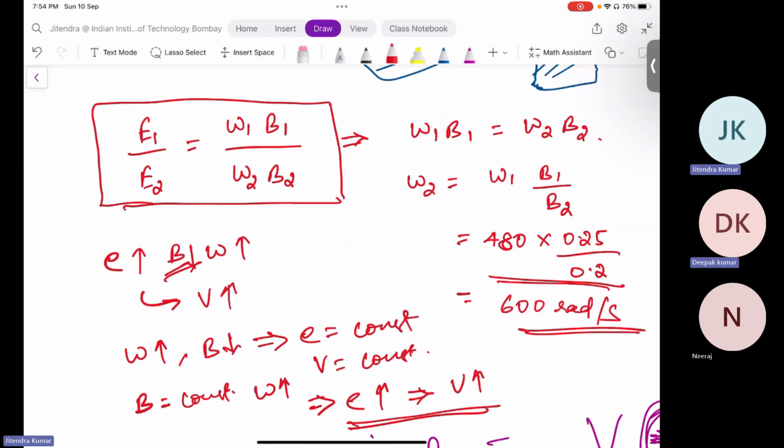Sir, ceiling fan application. Ceiling fan, no, again, because there you don't go beyond a certain speed; you regulate using a regulator. In BLDC fans, you reduce the frequency, and that is why your speed reduces. But here we are increasing the frequency essentially, since we are increasing the speed. But we have to maintain the voltage, because once you have provided a battery of certain capacity, you cannot surpass that battery.